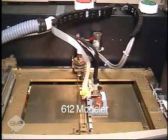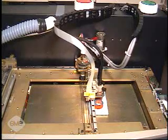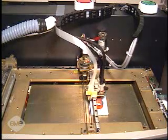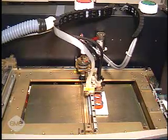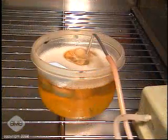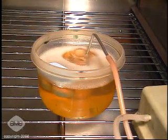The 612 modeler uses 2 print heads, one to build up models using a proprietary thermoplastic, and the other to build up supports using a proprietary wax. These supports are designed to dissolve in solvents without damaging the model material.